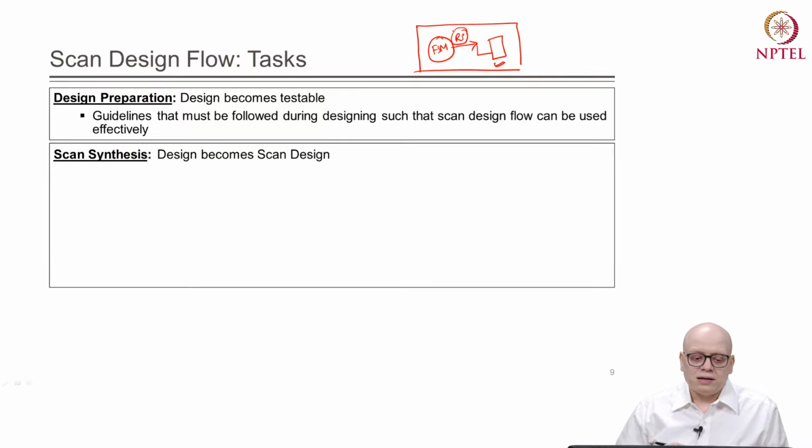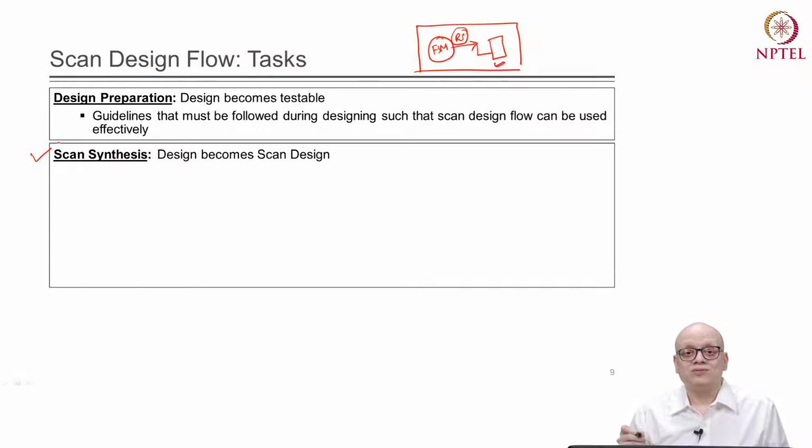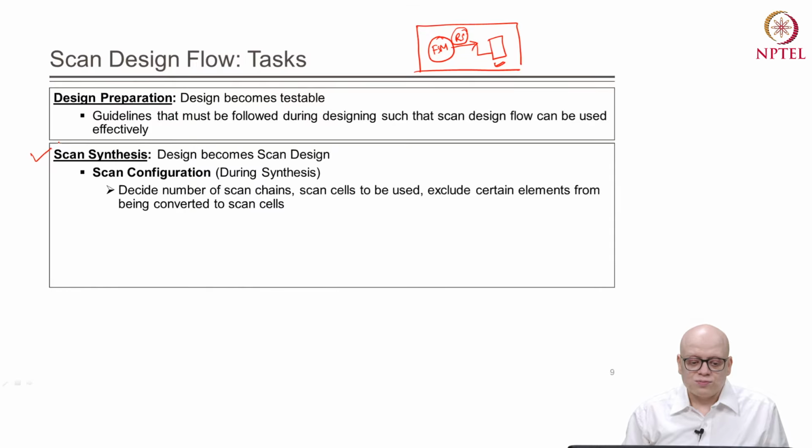Now, later on when we have the netlist, we do scan synthesis. So, in scan synthesis, the design becomes a scan design. So, we are inserting features or making design modifications to implement the scan design methodology. In this, first we need to define the scan configuration, meaning how many scan chains we want in our design.